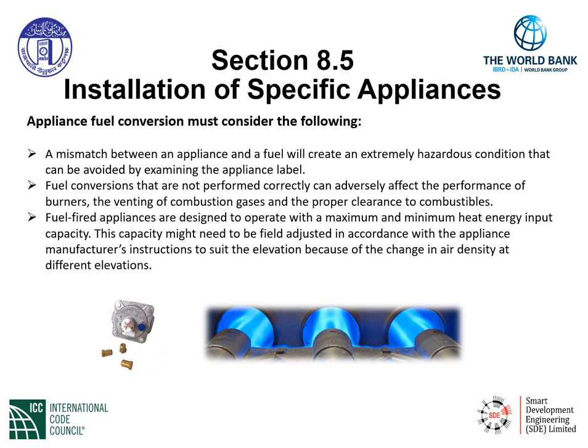Another consideration is that fuel-fired appliances are designed to operate with a maximum and minimum heat energy input capacity. This capacity might need to be field adjusted in accordance with the appliance manufacturer's instructions to suit the elevation because of the change in air density at different elevations.